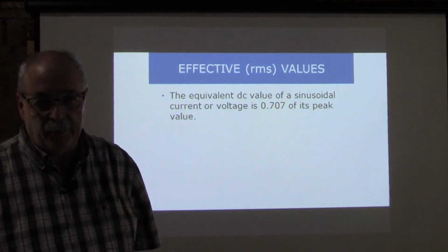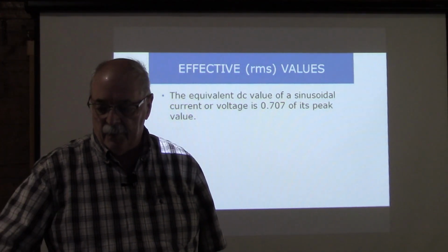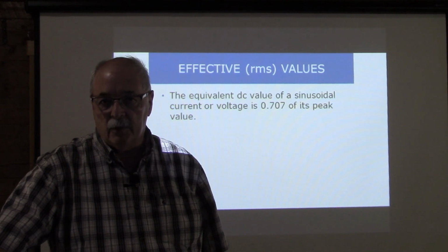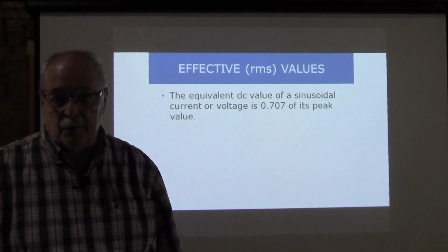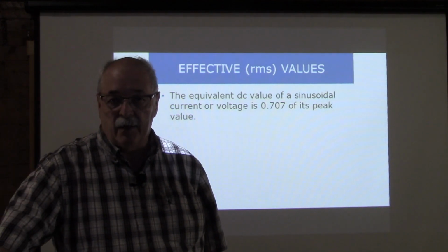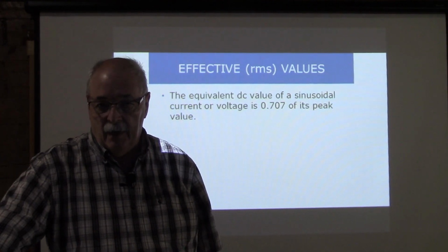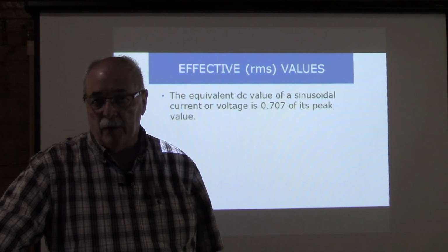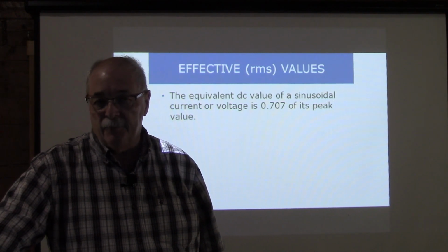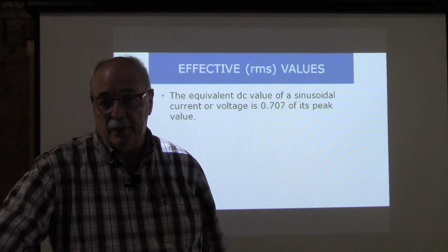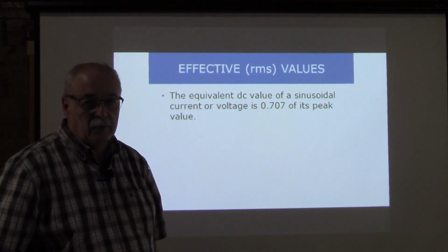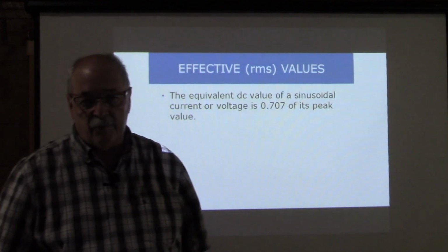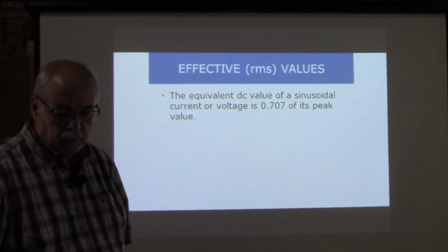You have to keep in mind what voltage you're using, if it's RMS voltage or a peak voltage or peak to peak. Somebody might even make this system sound even greater by taking the 170 and selling the system and saying, oh, it puts out 340 watts peak to peak. I mean, you can play games with the numbers, but in the lab, you're going to do a lot of conversions back and forth. So get used to converting back and forth between those values.